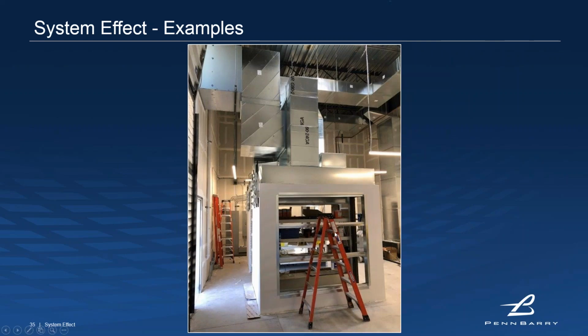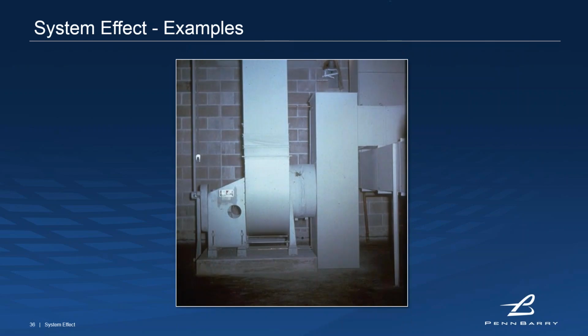Here we have someone who has done something really interesting with dampers and who knows what. I'm not even quite sure what's happening in here, but we've got all sorts of crazy transitions coming into this plenum box. Another situation where maybe just moving the fan a little bit further away would give us that space to have some better corners. Having dead spots in a box like this is a horrible thing.